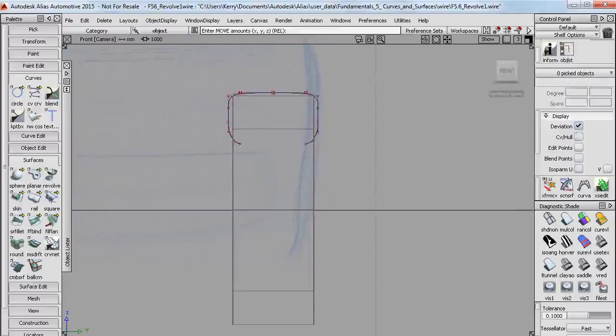I'll create a very simple shape for the main wheel. So I'll just stretch an edit point curve from there vertically down to the grid. And I can have fewer CVs, so I'll just rebuild that. And now when I give it some shape, I need to be careful to keep these two CVs vertical to each other, or 90 degrees to the revolve axis. And I'll show you why that's important later.